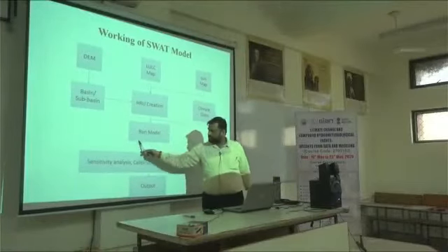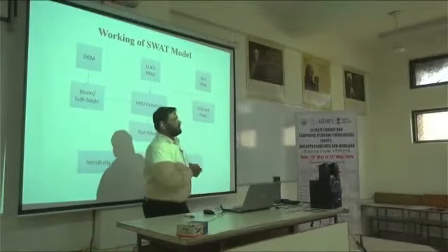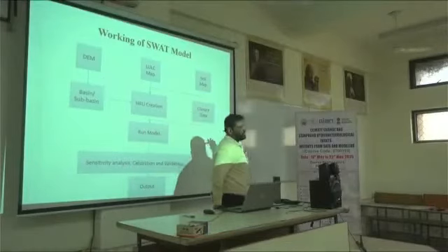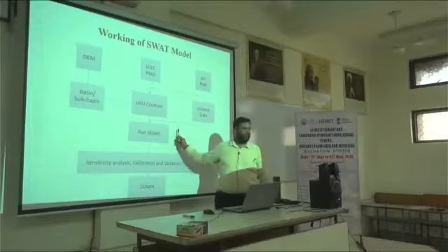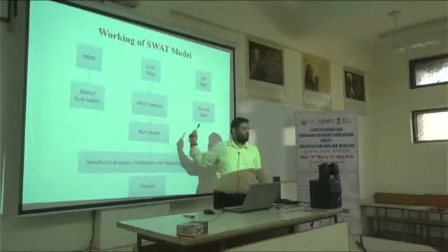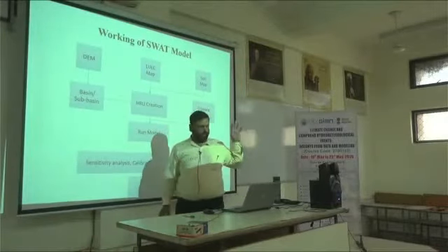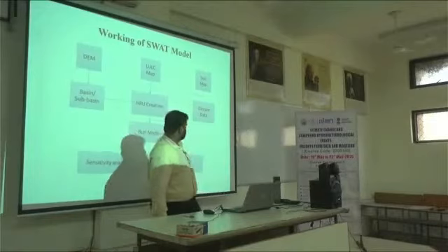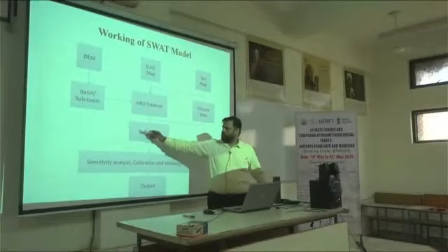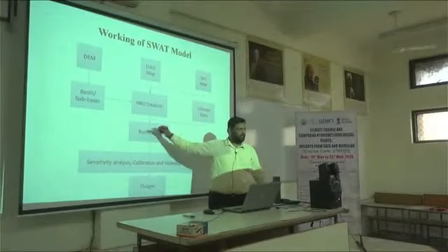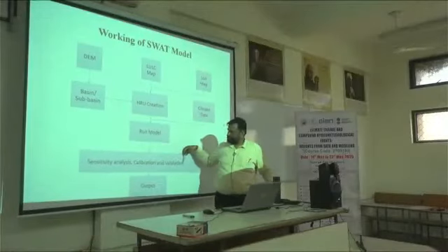After running the model, I'll show you that there is a module called edit SWAT output. In that module, we have to provide the management practices, what type of management practices are taking place. If we are interested in reservoir modeling, we can incorporate it here. Once we are satisfied that all these input parameters are working well, we go for run model, and then for calibration and validation.